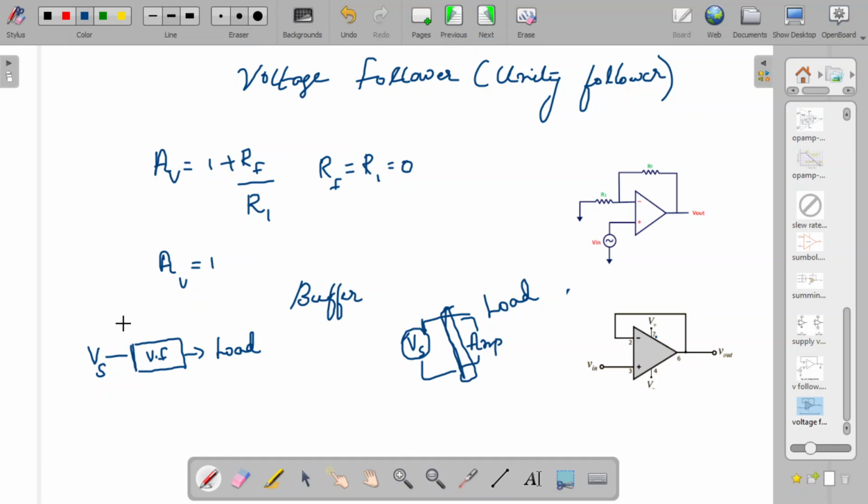So this op amp basically has very high input impedance, input resistance, but the output resistance is very low. So output resistance is very low in the case of an op amp. Since the voltage follower's output is what is being connected to the amplifier or any load, effectively the source resistance seems to be reduced. If the source has a very low output resistance, the loading effect which I said earlier will not take place. That is actually a favorable condition.